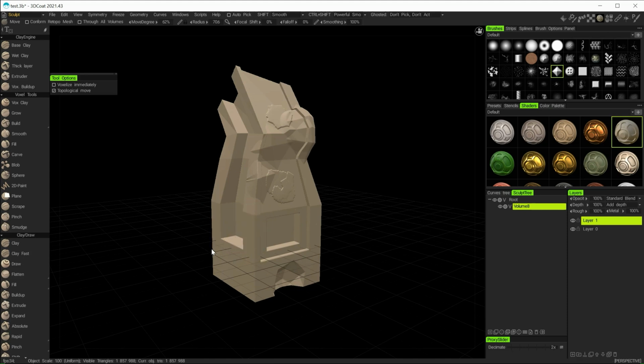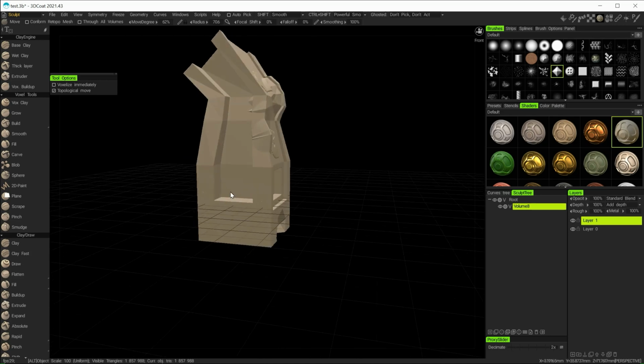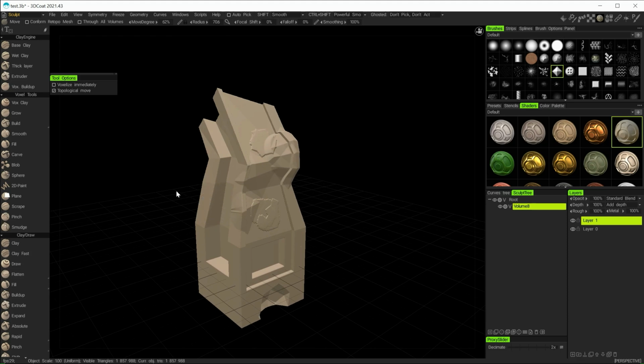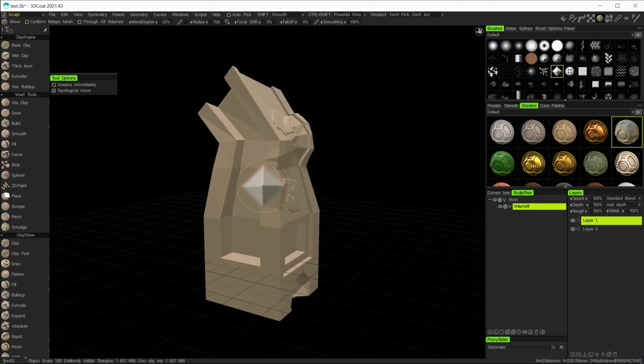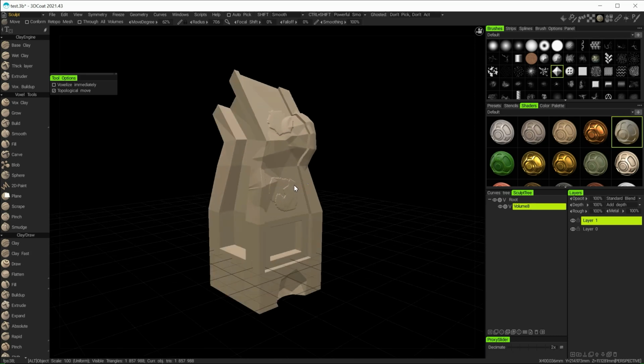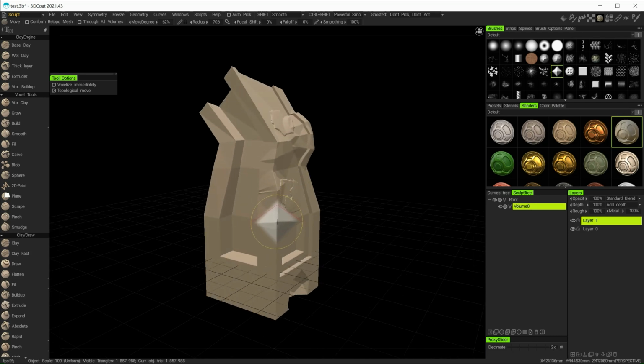So all we've done, just to summarize, is we've created a model in the modeling room. We've used some Booleans to cut out some various shapes, and then extruded some shapes out. And then we've tried two different methods of bringing that object into the Sculpt Workspace using the Sculpt Objects palette as a transporter, and we've brought those objects in both as a surface object, pretty much like what you get inside of ZBrush, and then we brought it in as a voxel object, which is pretty similar to a Dynamesh type of object that you get in ZBrush as well. So I hope you found that useful, and see you in the next video.